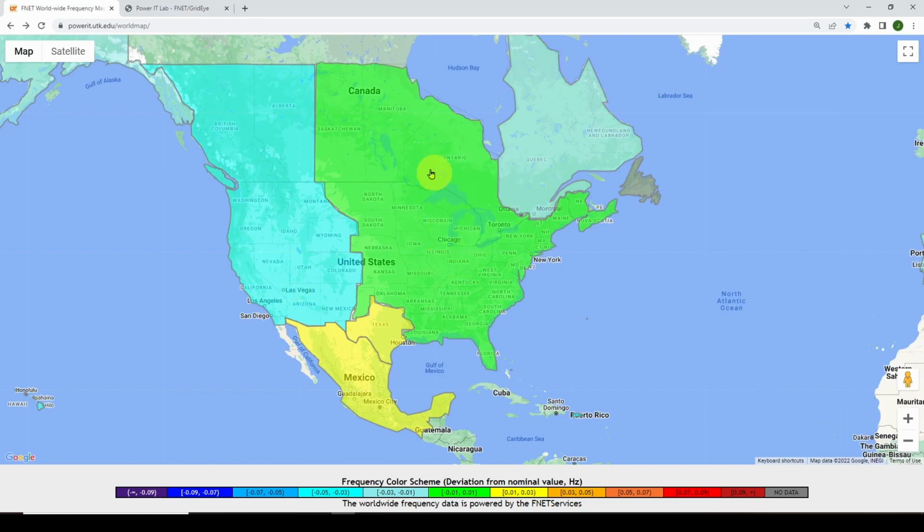Over time, they have decided in the US to break up the grid into an eastern half of the US, including parts of Canada, a western half of the US, and for whatever reason, Texas has their own isolated grid. Now, when I say these grids are isolated, technically they may have interconnections between them. For example, there are some interconnections between eastern and western US, which are DC, direct current, which means they're not tied together synchronously, but they can provide some power across them. For all intents and purposes, these are isolated grids, okay?